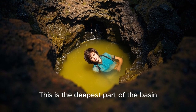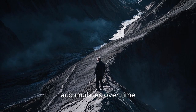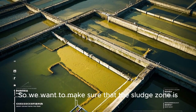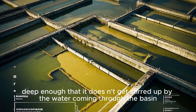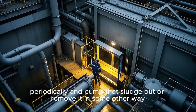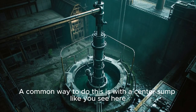This is the deepest part of the basin, and it's where all the settled solids, otherwise known as sludge, accumulate over time. Now, we don't want that sludge to get resuspended and go back into the water column. So, we want to make sure that the sludge zone is deep enough that it does not get stirred up by the water coming through the basin. But we also need to be able to access that sludge zone periodically and pump that sludge out or remove it in some other way. A common way to do this is with a center sump like you see here.